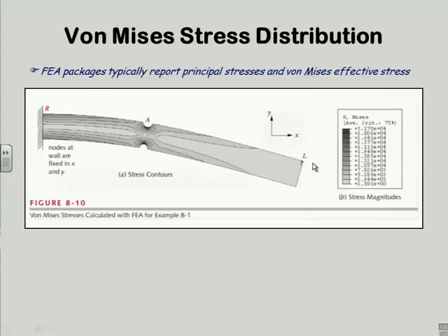Now that was a point force, and this goes to your point. There's a point force applied to the last node on the corner at essentially zero dimension, zero width. It's a point. And it's showing the stress concentration for the local load. You see the little dark spot in the upper right corner. This is probably with the high-level mesh. I don't remember. I didn't put a note here. Probably with a lot of elements in order to be able to see this.